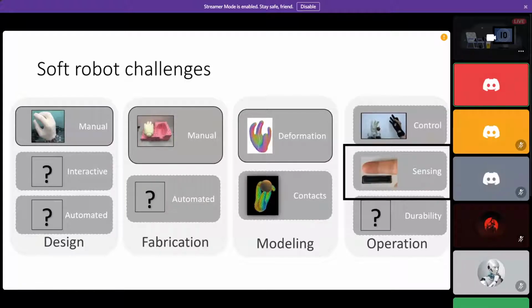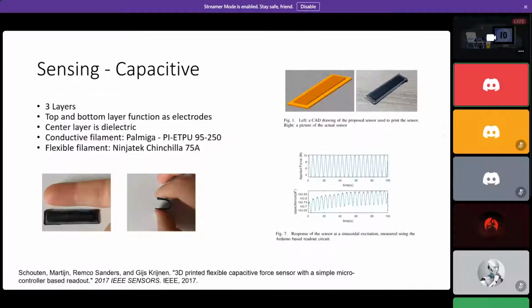And that brings me to the next point. With soft robots, it's often a problem to incorporate sensors, because just like the robot itself, your sensors need to be really soft. And so that already is a pretty big constraint on the sensors that you can use. The robots that I showed so far don't have any sensors, and that's why all of the control that we did is always open loop, because you can't close the loop without any sensor feedback.